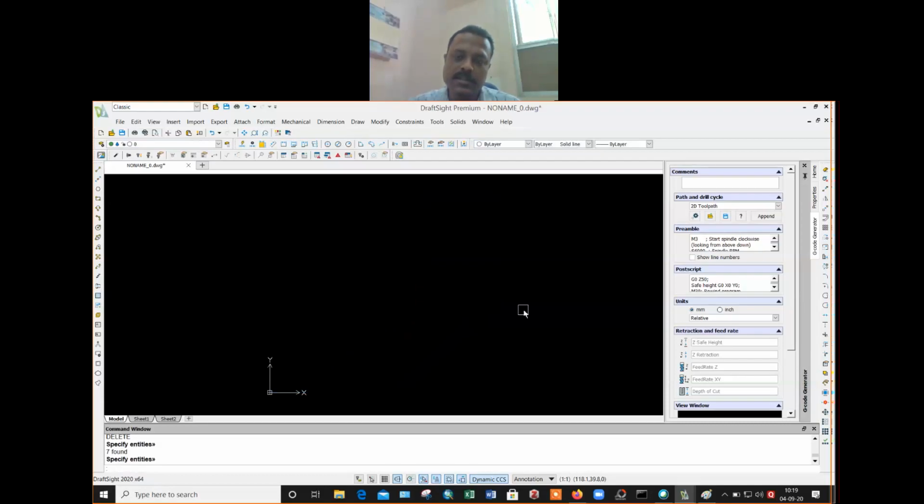It is gone. So in between you will learn some small commands. So now you have learned how to erase or delete. If I want to bring it back, just undo, type U, enter, it comes back.